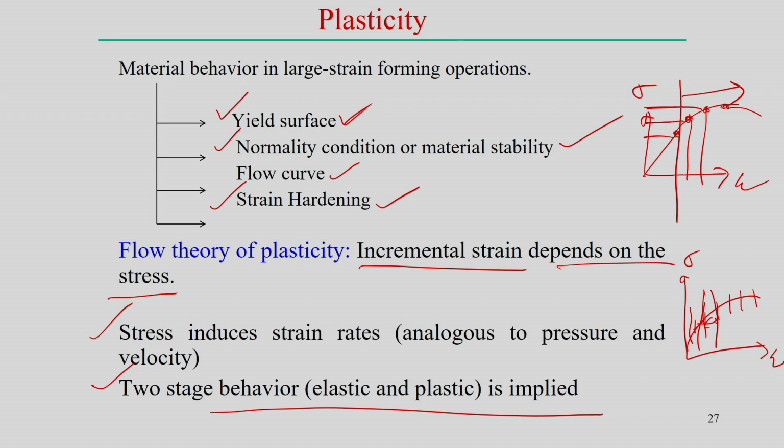So, there is an elastoplastic analysis in most of the manufacturing processes. For example, in the case of the bending process, there must be some amount of elastic spring back effect. So, we need to incorporate that elastic spring back effect, then only can we get the actual plastic deformation needed to get a particular bend angle. That we will discuss during the material forming process module.